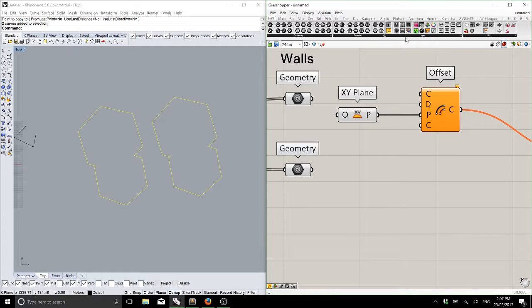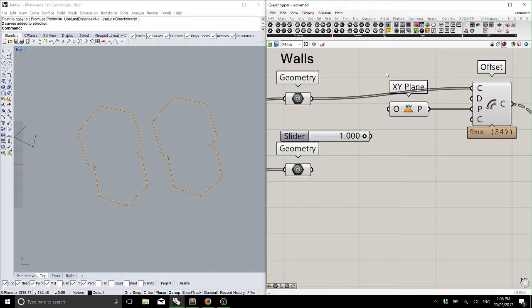So if I wanted to create a 1 meter thick wall that was offset in both directions, so one goes one way and one goes the other, what do I need to do to my offset to make sure that I can get that centered? Not quite. You divide the distance by 2 and minus 2. Yes, exactly. That's exactly what you would do.